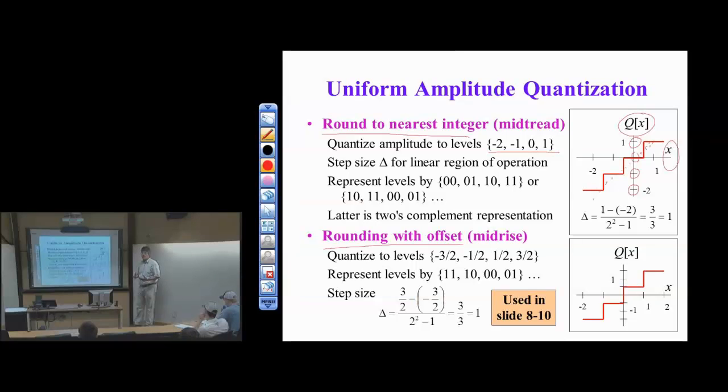It gives some very nice analytical results because it converts a nonlinear system into a linear one by approximating the quantization output as a scaled version of the input. Okay, we'll do that at a later time, not for today. If we fall outside this, called linear region, if you will, then we get clipping. And so if X is greater than 1.5, we're going to clip.